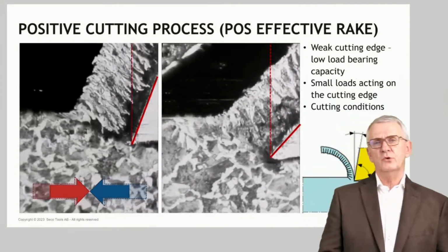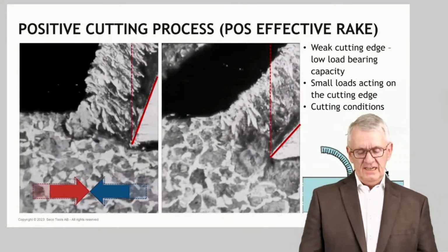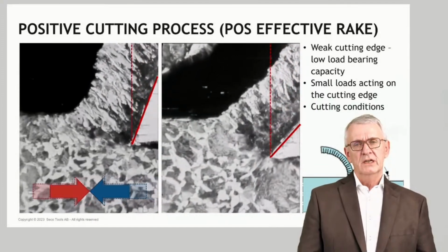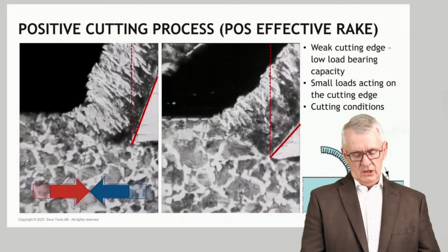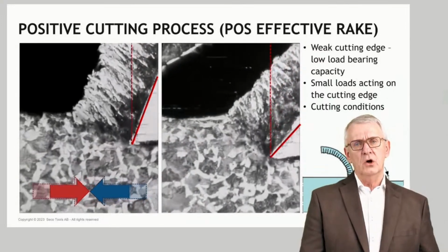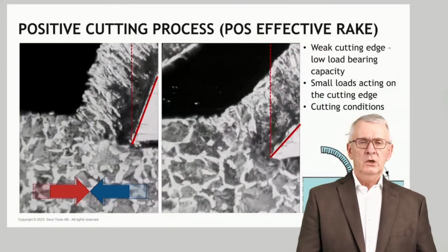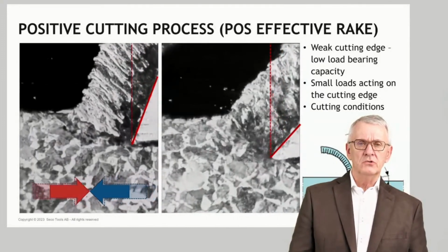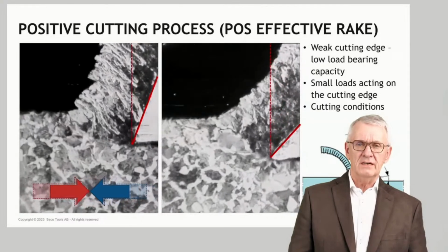And in case of positive cutting, again, it's about finding a new balance point. A balance where the loads acting on a tool are lower, but the ability for the tool to withstand the loads is also on a lower level.